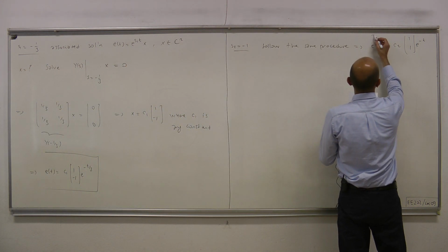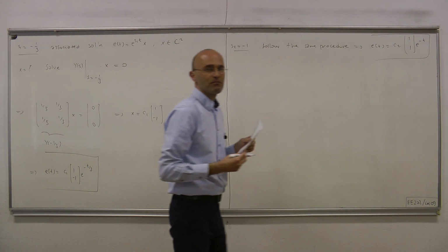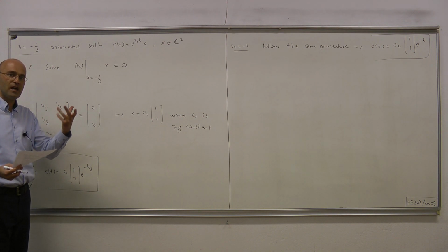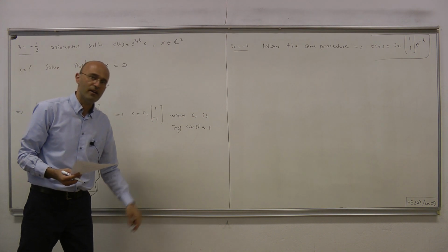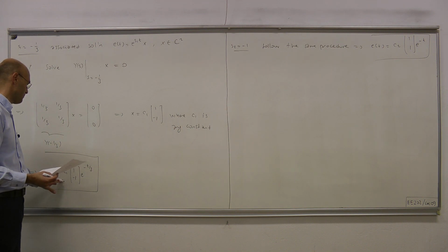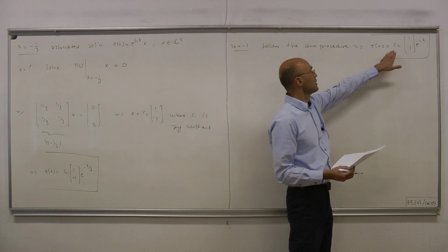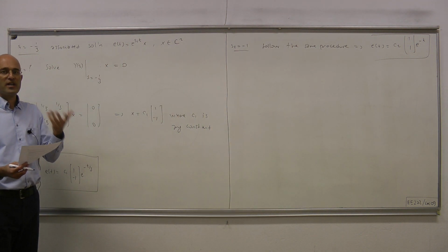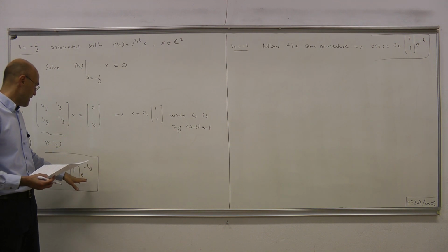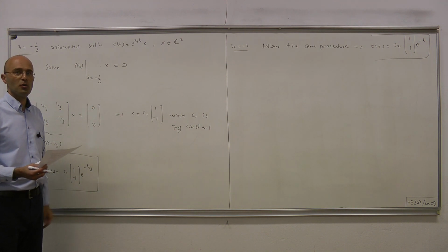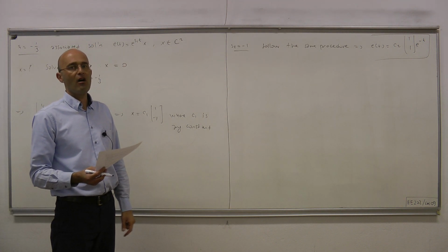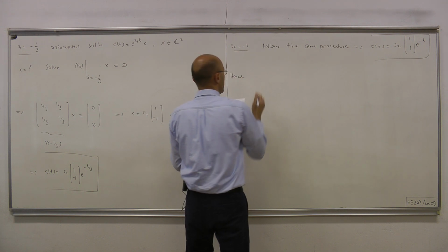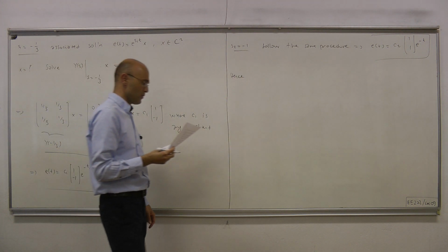So let's also put it in a box. Now this solves our homogeneous differential equation, namely the node equation. Why homogeneous? Because we don't have any input in the circuit. This too solves our node equation. And since we're dealing with an LTI system, we can apply superposition. So that means any linear combination of these two solutions must itself also be a solution. And that takes us to the general form of solution for our circuit.